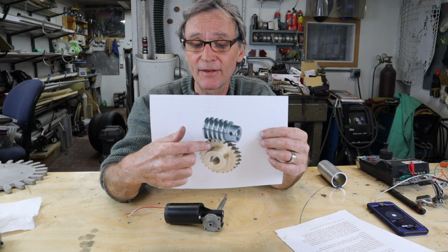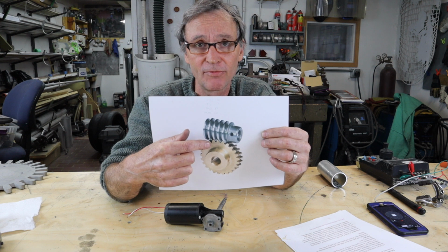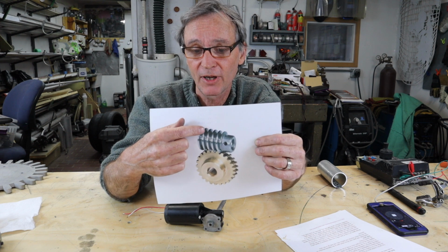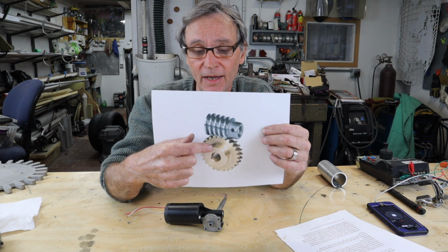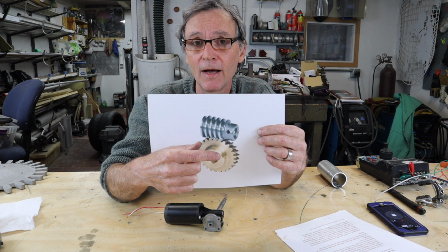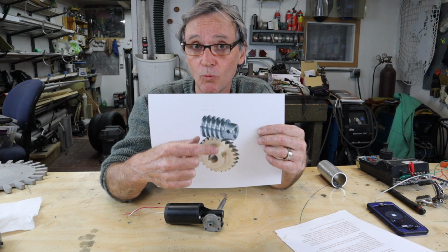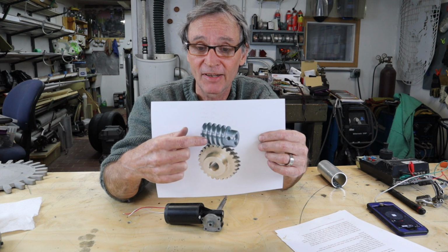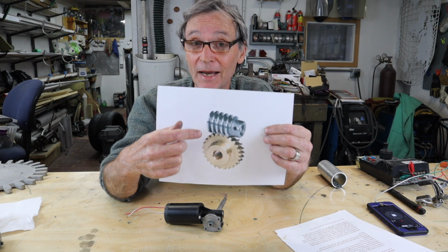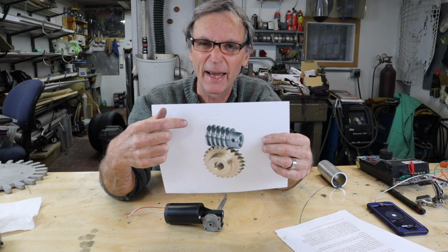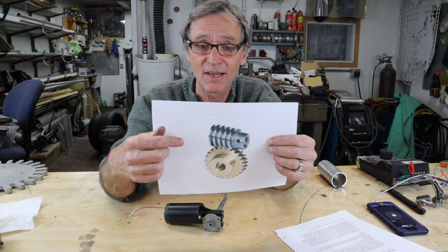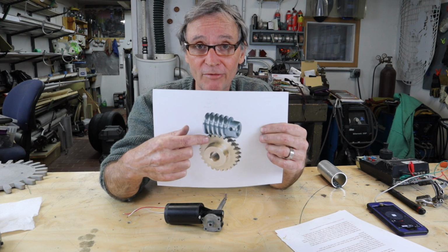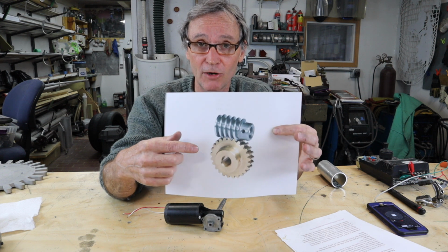So if you add these to each other, if you put another set of worm gears after this, you'd get 625 to 1. So this would go around 625 times. It would go from this to another worm gear, and it would go round once for every 625 times this went round. If you added another set, you'd get 15,625 to 1. And added another set, you'd get, it's written on the back, I'm cheating, 390,625. If you had put 4 of these together, you get incredible reduction.